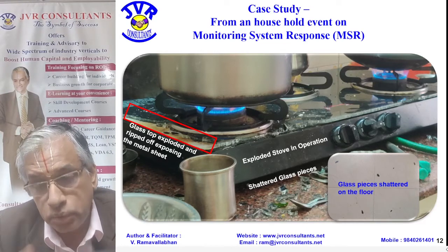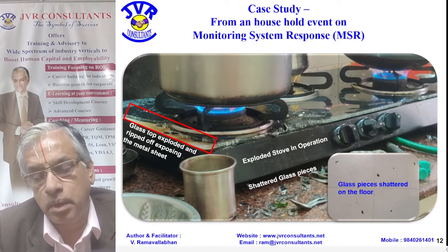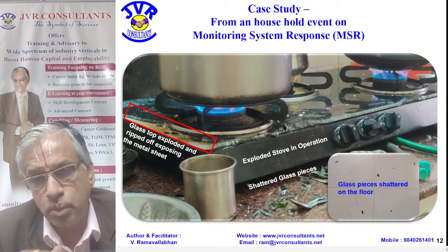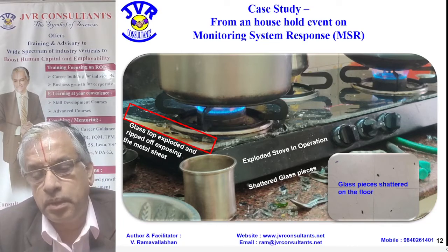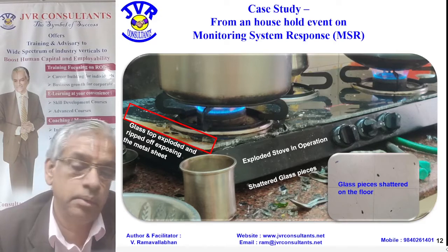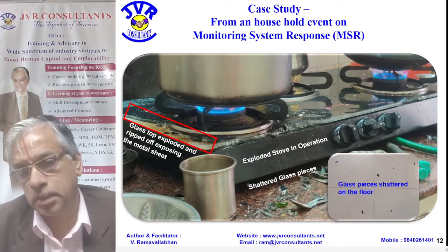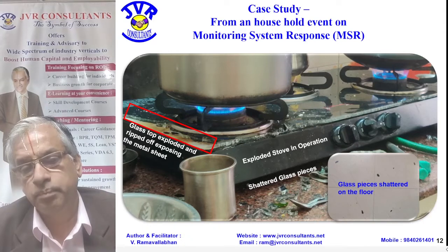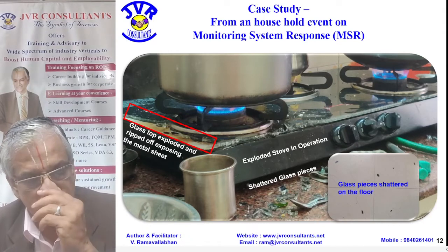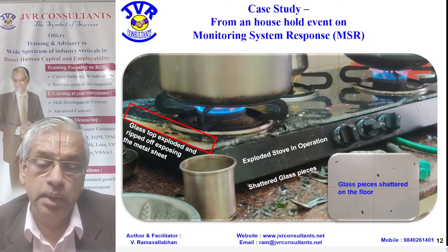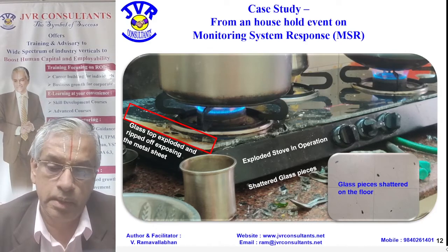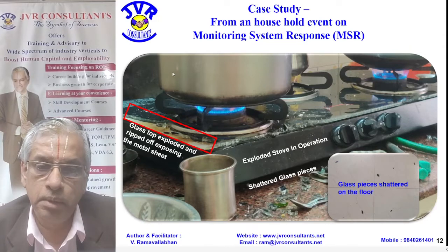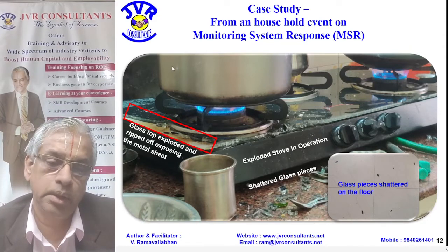So here, at the user end, in the user operating condition, three stoves are on. In this condition, this has happened. Now you have to do research here. The AIAG VDA first edition has recommended a format for this, the MSR. You document in that. Then this should be the input for the design FMEA. There you go and update it later so that your FMEA gets improved and your product reliability improves.